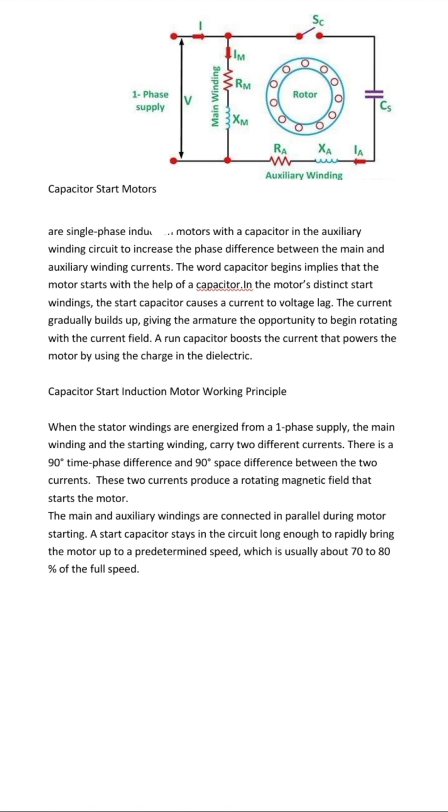Note that the motor will not work properly if the centrifugal switch is broken. If the switch is always open, the start capacitor is not part of the circuit, so the motor does not start. If the switch is always closed, the start capacitor is always in the circuit, so the motor winding will likely burn out. If a motor does not start, the capacitor is far more likely to be the problem than the switch.